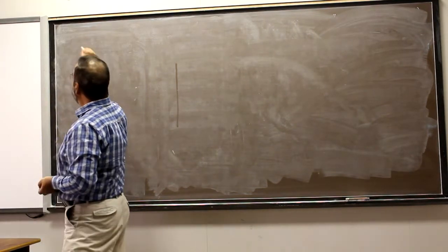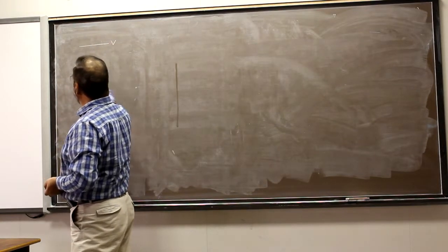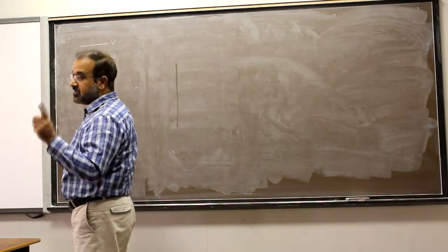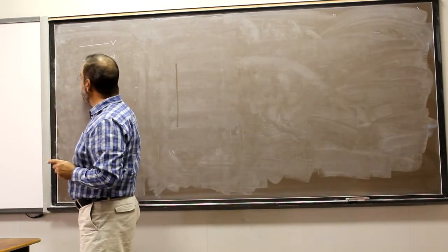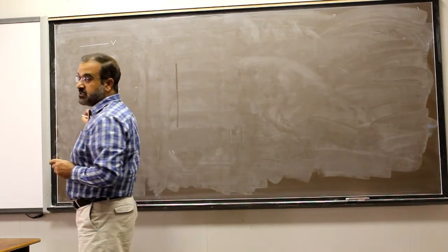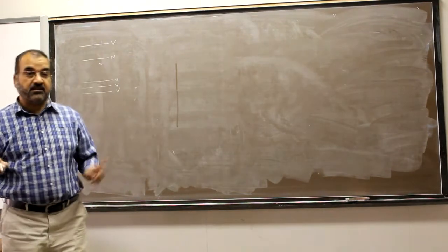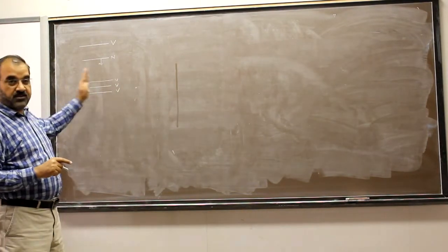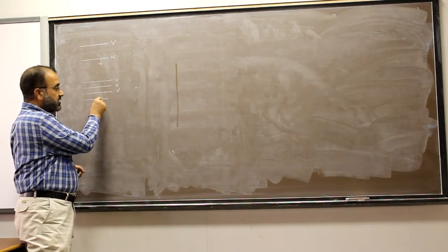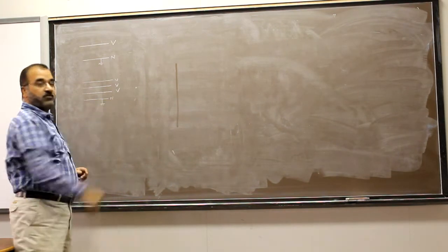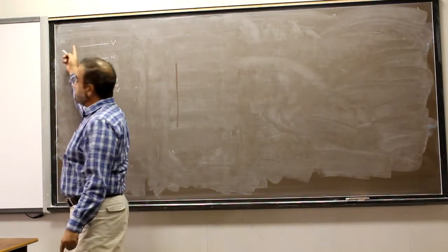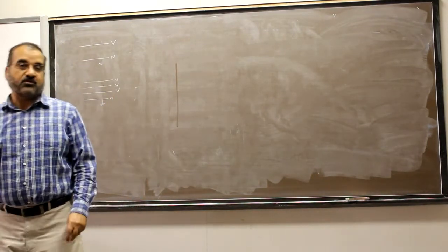So if I say single phase, as I told you, there will be one with the voltage and one with the ground, or it will be known as a neutral. Similarly, when I say three phase, there will be three conductors with the voltage, and the fourth is optional depending on the connections, from where the power is coming. The fourth conductor will not have any voltage, but it will be either grounded or known as a neutral conductor. Now, how do you generate this single phase? It is already single phase.